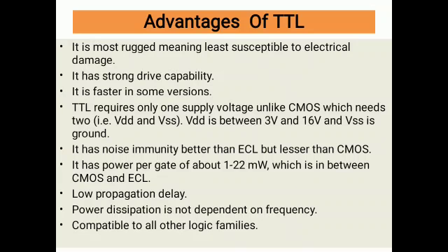So the advantages: it is most rugged, meaning less susceptible to electrical damage. It has strong drive capability. As we had seen, its fan out is 10 and fan in is 12 to 14. It is faster in some versions. TTL requires one supply voltage, that is an advantage.